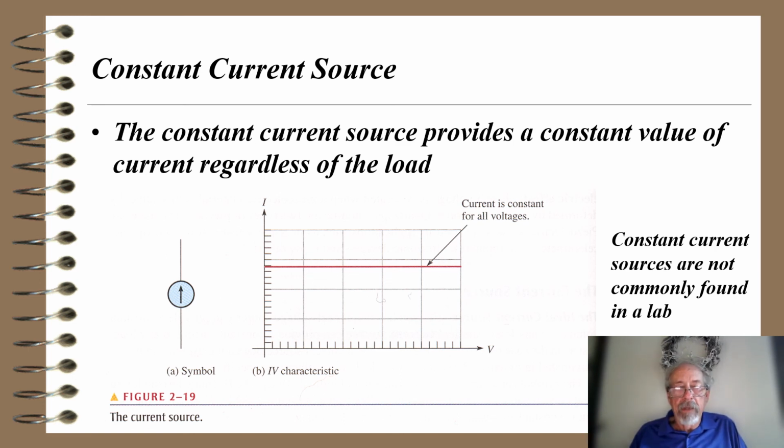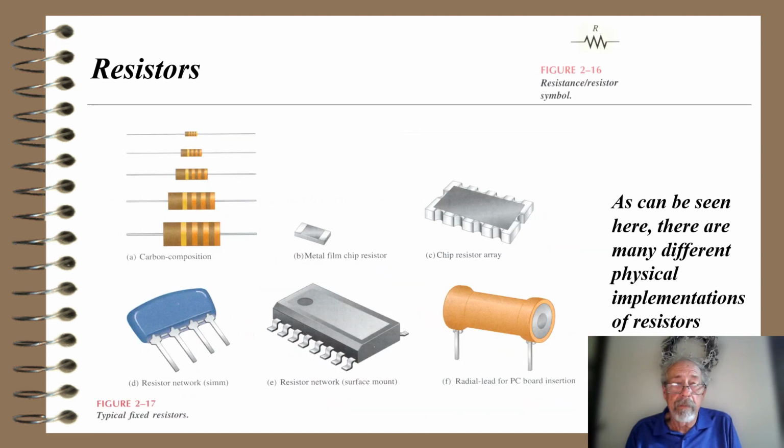And it turns out that, again, it doesn't matter what you attach to the thing, but that's what makes it kind of crazy, because I could put a 1 mega ohm resistor, and if I had a 1 amp constant current source, I'd be producing 1 million volts across the 1 mega ohm resistor, which most likely would fry the resistor. But again, we sometimes have these ideal sources to model what's going on over limited ranges for, say, in this case, semiconductors, which is why this thing was invented.